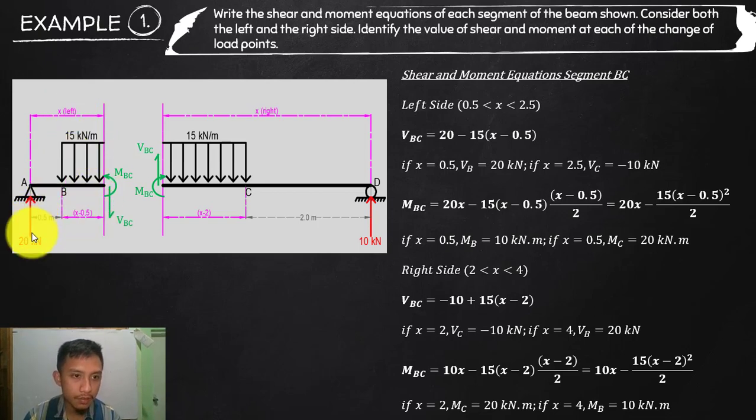Okay, so again, go back to your shear. So going up is 20, positive, and what else? If I try to convert this one into a concentrated load, that is 15 times the distance or the length of that, which is x minus 5. Okay, so now you have a variable in your shear equation. So you can simplify this further, or you can take it as is.